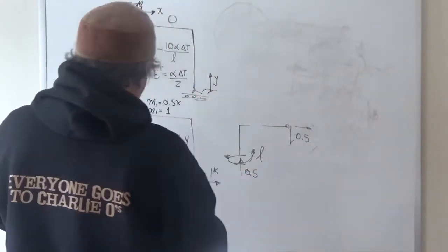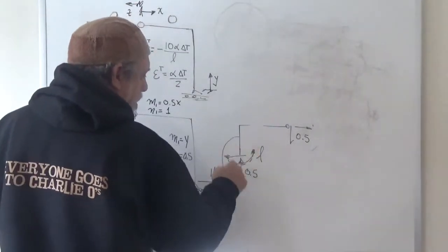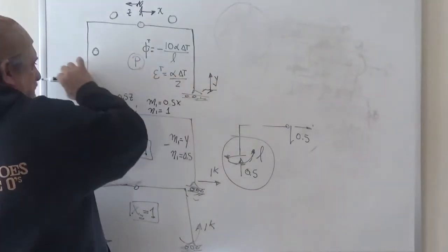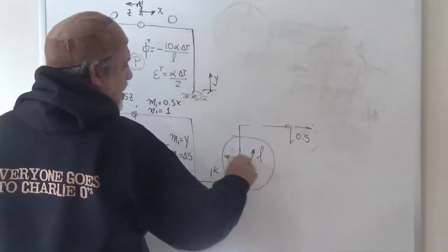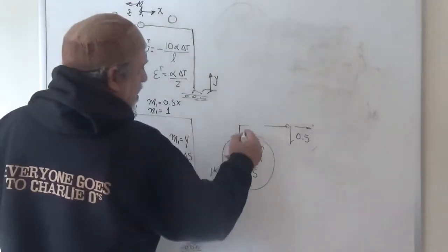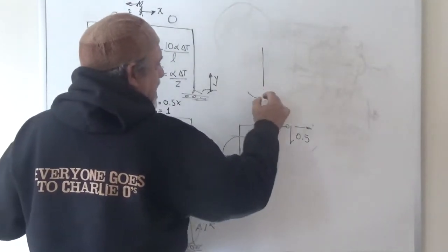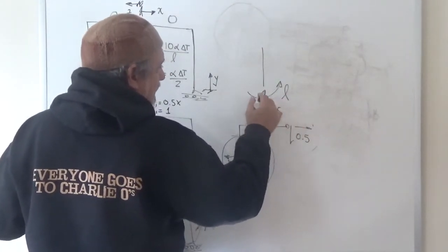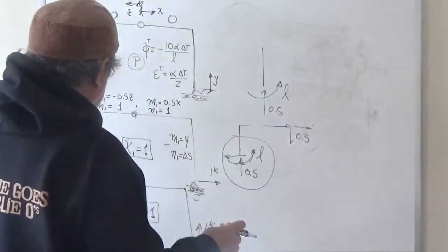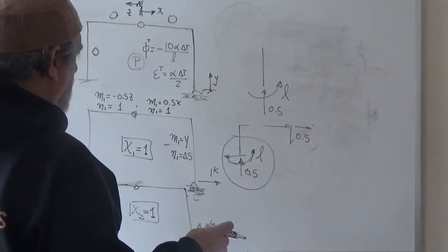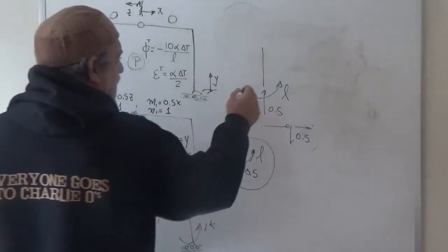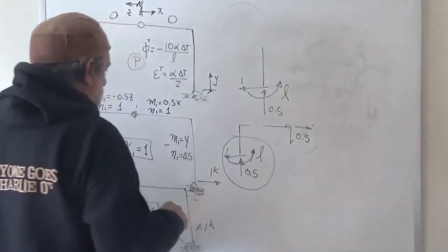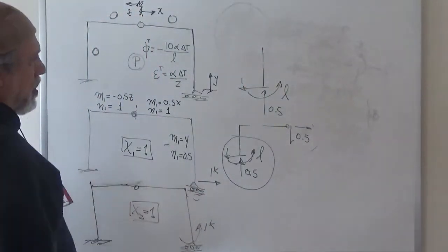So what I'm going to do now is to take this bubble. Why? Because I already selected a coordinate that is at this level moving up as y, so I can still call this y and it would be legal, right? So I can say that that part has a moment L, has an axial of 0.5, has a shear of how much? No, it has a horizontal. Obviously the horizontal had to be 1. I erased it a little too soon or didn't put it. But it has to be 1, because I can see from the sketch that's the only other horizontal, right?